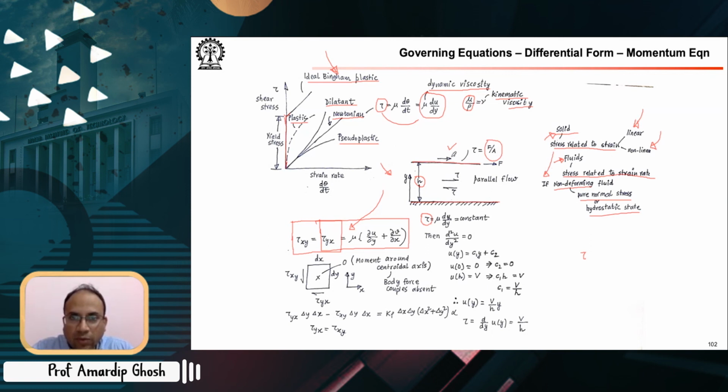And if you go from cross section to cross section in experiments, for example, you will see that the profile doesn't change. So the profile has actually a very interesting feature, which I will talk about soon. The profile doesn't change from location to location. So essentially, then the net force acting on the fluid element is zero. So there is no pressure difference acting on this fluid element.